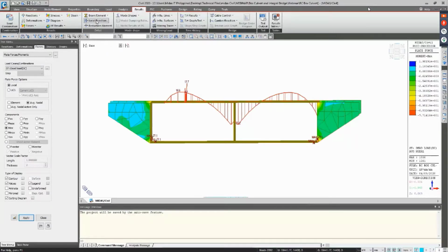These resultant forces and the acting point are calculated on the basis of all the nodal forces included in the selected plane. So if you need a detailed analysis for a specific part of a structure, this function calculates the member forces for the structural design.